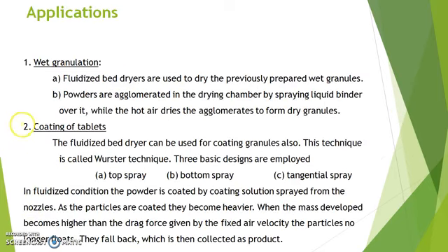Applications of fluidized bed dryer. Mainly there are two. In the wet granulation method, fluidized bed dryers are used to dry the previously prepared wet granules. Powders are agglomerated in the drying chamber by spraying liquid binder over them, while hot air dries the agglomerates to form dry granules.